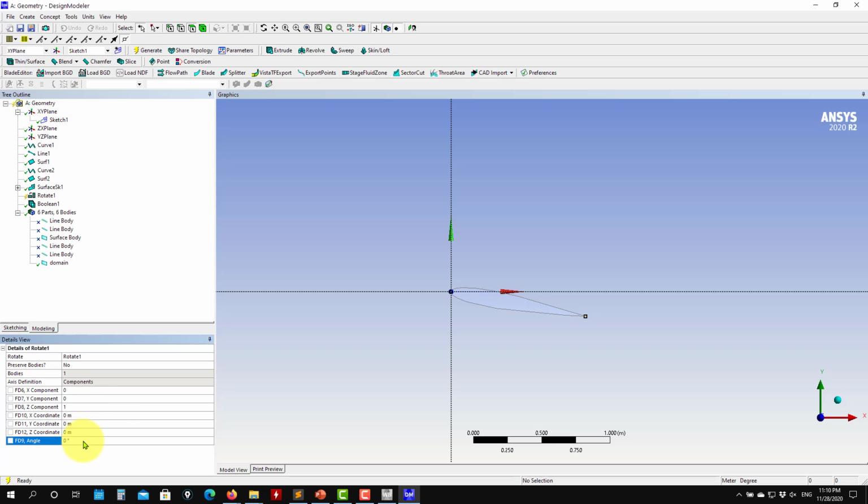So now you have something that is parametric, very handy. There are many ways also to do parameterization. I'm just showing you one way, but there are many ways to do a parametric study and to add automation in your simulations. At the end of the day, you would like to run, let's say, hundreds of simulations. You don't need to do this manually. You just define what your parameter variables are, and then somewhere in the Workbench you will define how many experiments you want to run, and then Ansys will do it automatically.